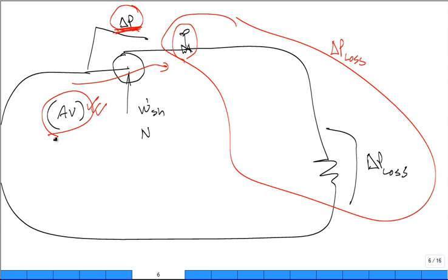And in this case, the efficiency continued to go down, down, down until all of that shaft power went basically into Q dot into the fluid, heating it up. And if you just let it go, it'll get hotter and hotter. It has to dissipate that energy to the room, or it'll burn out a bearing or something else. But it can get that water toasting hot.